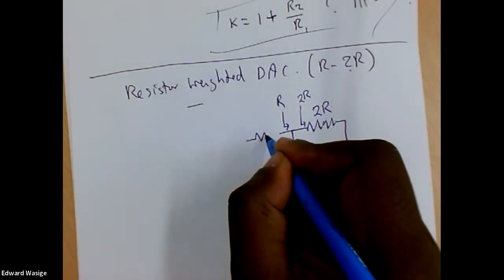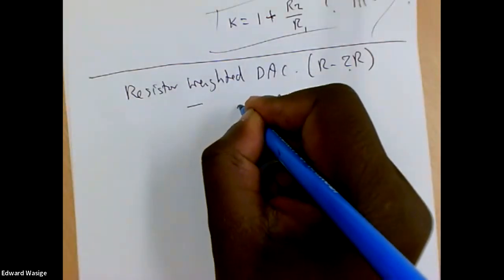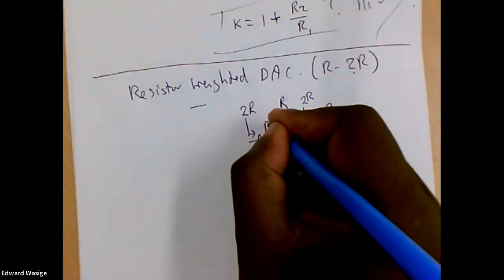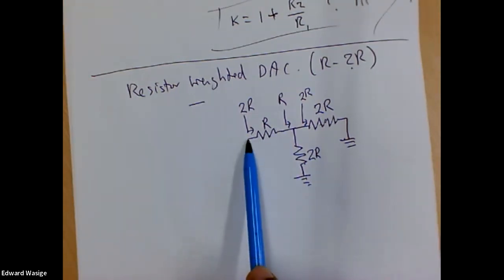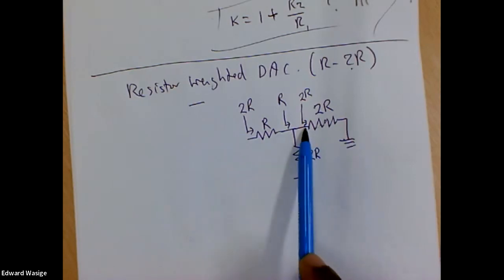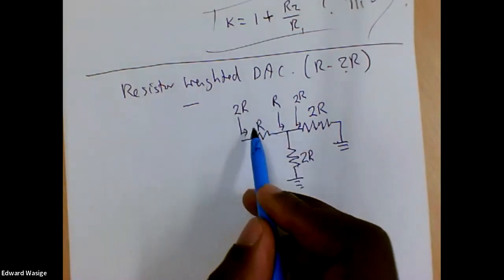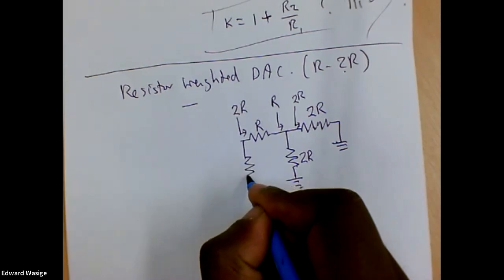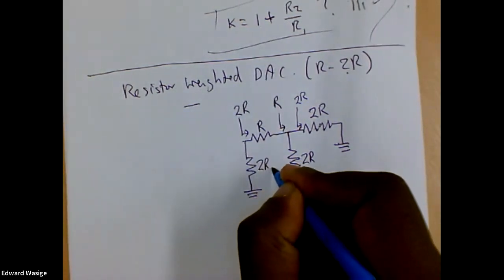And if I introduce another resistor there, I could make this 2R so that it looks like that. If you think about it, the resistor value that I need to introduce there is R. So if I introduce a resistor R there, the input resistance I see looking towards the right is identical to the resistance I see from here towards the right, which is R. And because the resistance to the right there is R, I can create another branch here to ground, and its value is 2R.